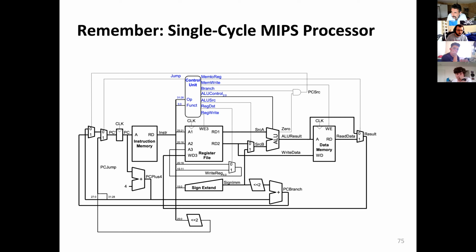Can I just say what I think on this? It may not be right, but I think I got something. Yeah, absolutely. So from what I realized, the single cycle goes for all the instructions, so we don't need the multiplexer because it runs at once. But for the multi-cycle, we need it because we need something to direct which step of the instruction to operate with the clock cycle. Otherwise, it wouldn't know how to save the time because it wouldn't have anything to direct it to the step of the instruction. That's 100% correct.